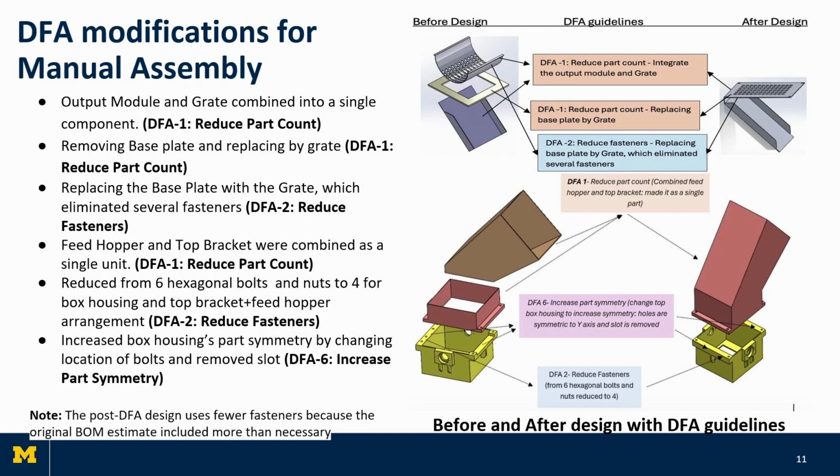The right side of the slide shows the CAD before and after design. Here are the DFA guidelines. By combining the output module and grate, removing the base plate, and merging the feed hopper with the top bracket, the rule DFA1, reduced part count, was applied while maintaining functionality.